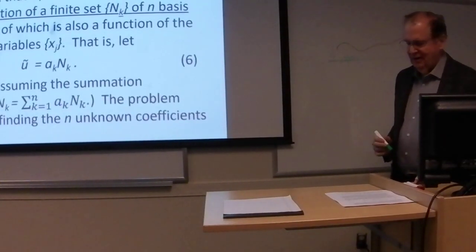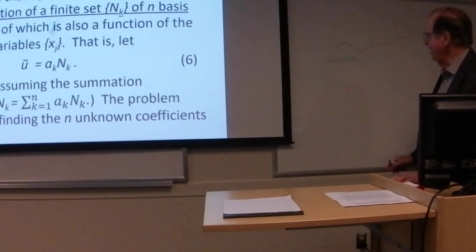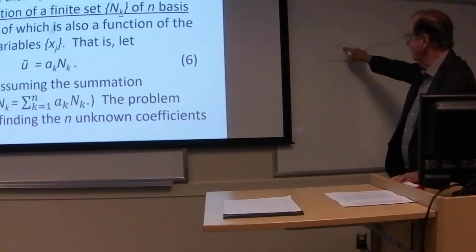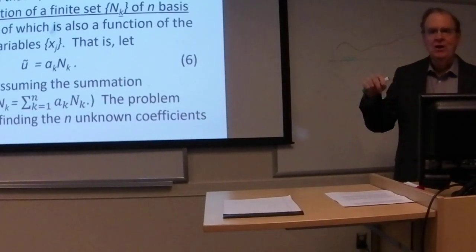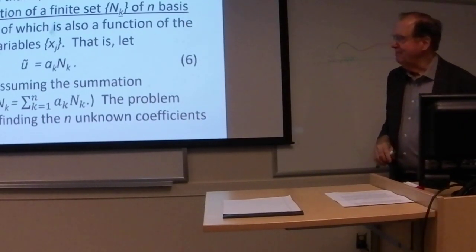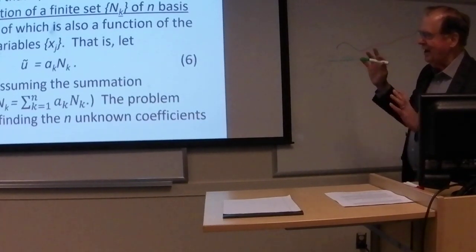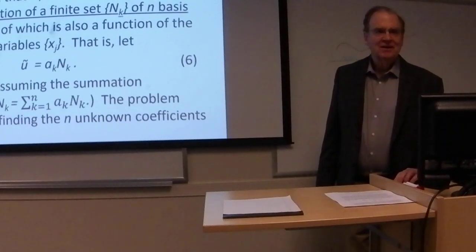So that's what the finite element method is. It uses these local basis functions. So in a 1D situation, you can approximate your function in a piecewise linear way with these little tent functions, as they're called because they look like a tent. They're 1 at the node and 0 at the neighboring nodes. Anyway, it's important to realize that an important aspect of the finite element method is working with an approximate solution of this kind, in terms of local basis functions.